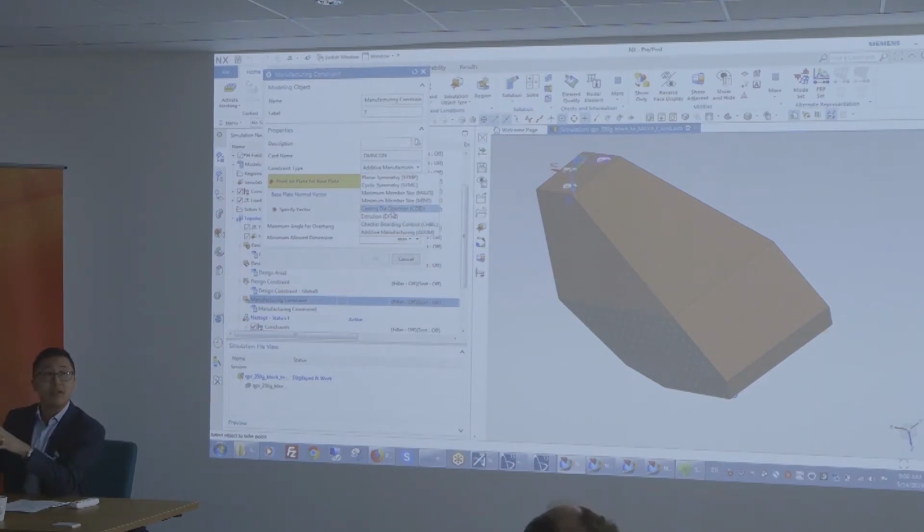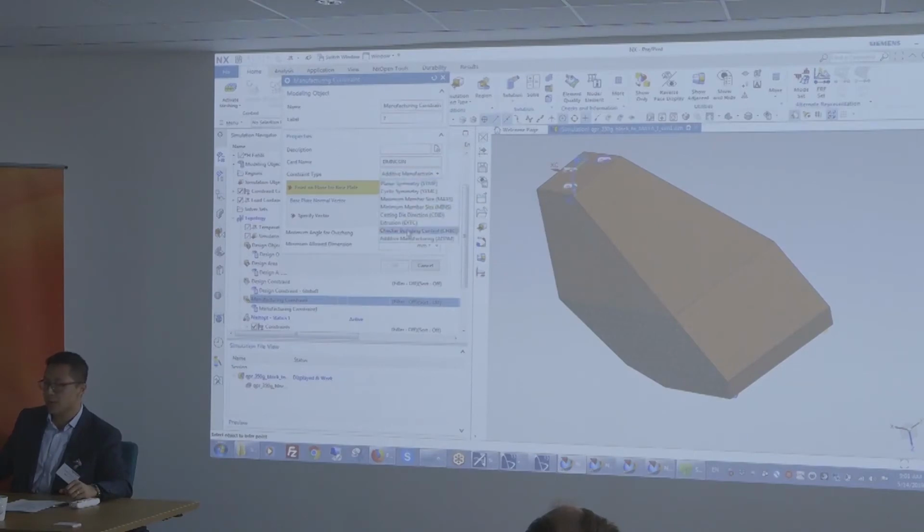But we have another module that's called designer topology optimization. That's less focused on simulation, so the excitation that you can put is quite simple. It's static analysis or modal analysis. But then it has more of a manufacturer's intuition in it. The idea right now, in the product roadmap that Joe had shown, is to integrate those kinds of manufacturer intuition constraints into this one here. But we do have some interesting manufacturing constraints that we can leverage. Very good. So I did create my symmetrical manufacturing constraint.